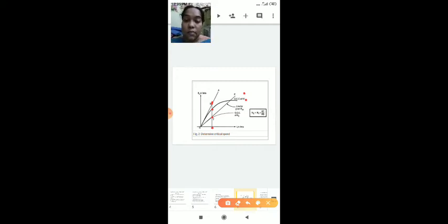Here the tangent line is important. This tangent line is the critical resistance. That critical resistance touches this open circuit characteristics curve. Then we draw a straight line here. This is RS. The critical speed is the speed for which the given shunt field resistance represents critical resistance. That speed is called critical speed. Here OA is the critical resistance. NC is N1 into RT by RS.